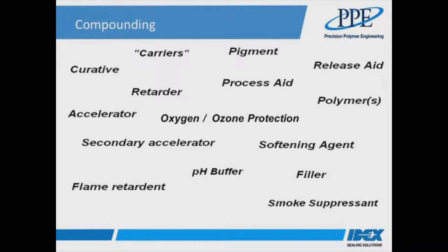For semiconductor-related applications, which are really among the most stringent for any elastomer material, the aim is to try to limit to a minimum the number of ingredients, and not only that, but the ingredients are carefully selected for process compatibility. At the same time, we still try to achieve the desired elastomer properties.